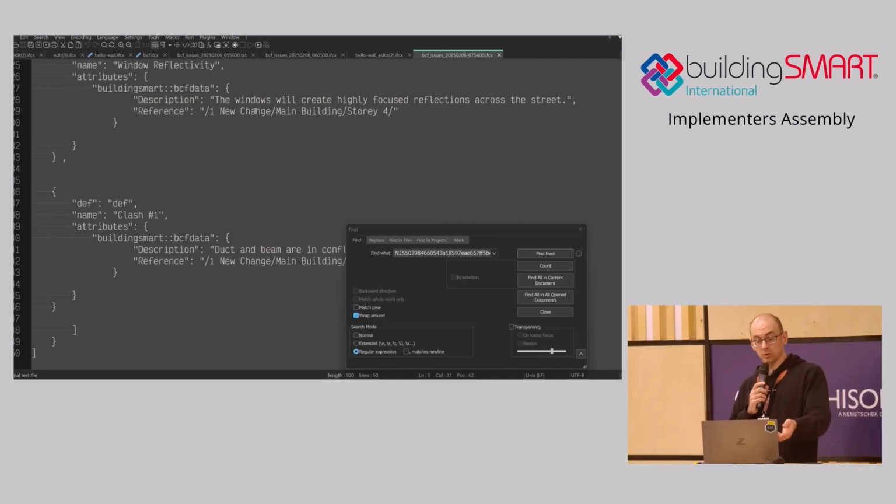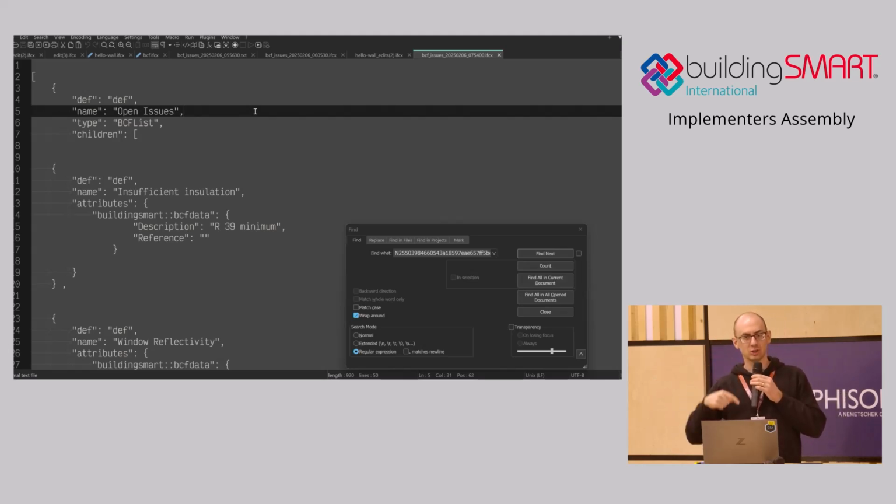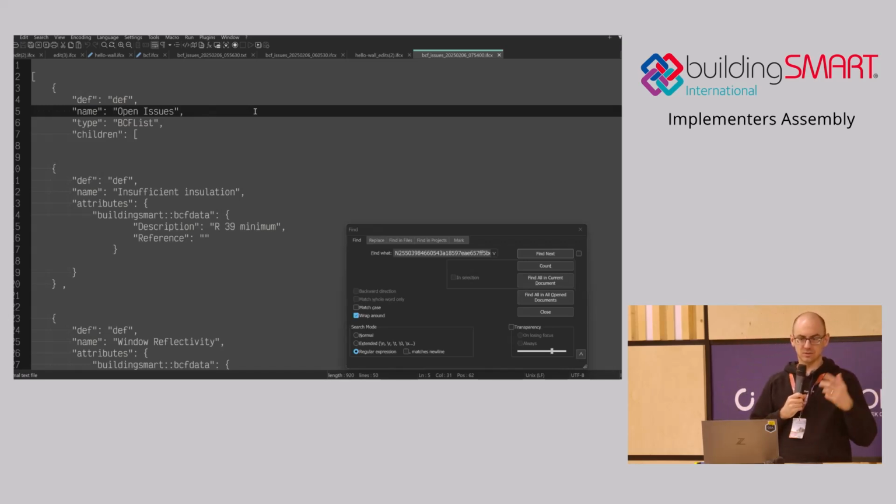Correct. And then what you could do is do exactly what we've done here and create a list of issues and then do an over with a BCF issue link on every affected object. You add a link to what it is. And if you do that onto a class that gets used 50 times, every single instance says, hey, there is an issue about this model. You've got some modeling issue in your family, so to speak. And that would just flag that everywhere.